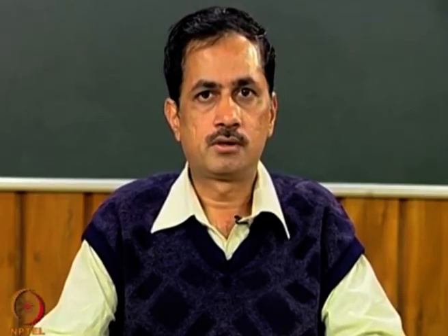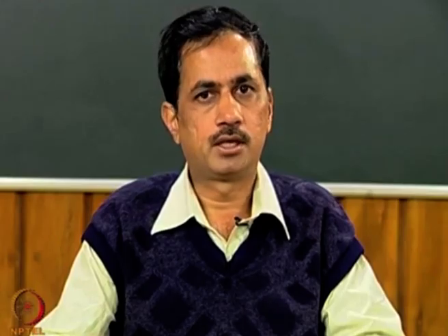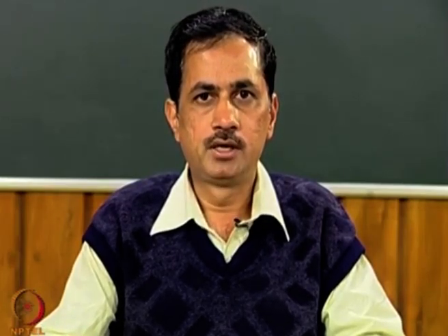So, first corresponding to the translational whirl and another is the conical whirl, and in both cases each and every particle of the shaft executes an ellipse. And we have seen that as we change the speed, for the linear case, the direction of the whirl changes. When we are below the critical speed, or in between the two critical speeds, and after the third critical speed, the whirling direction changes.